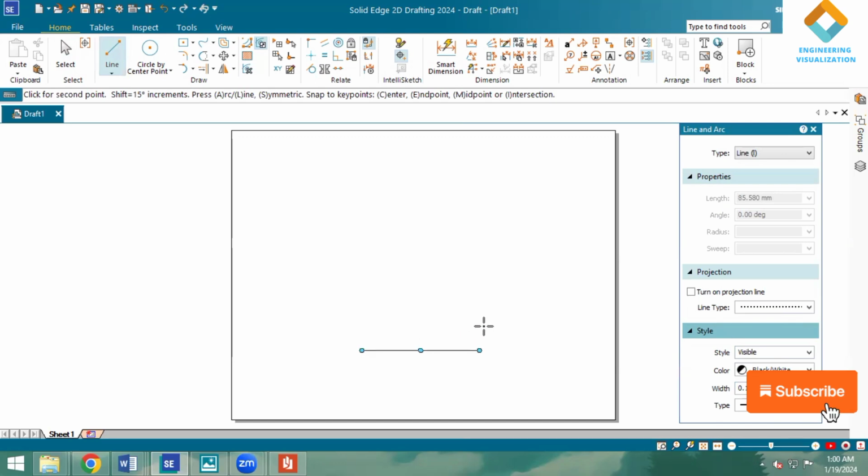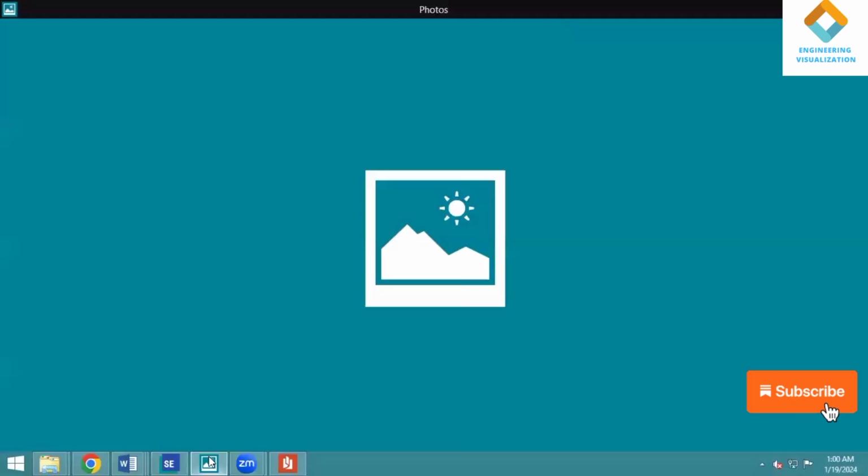From this reference point I'll draw one line, that is a line with an angle of 30 degree. So here I'll take 60 mm. Okay, and angle will take 30 degree, because in isometric we should use angle 30 degree. Okay, first I will be constructing a rectangular block.